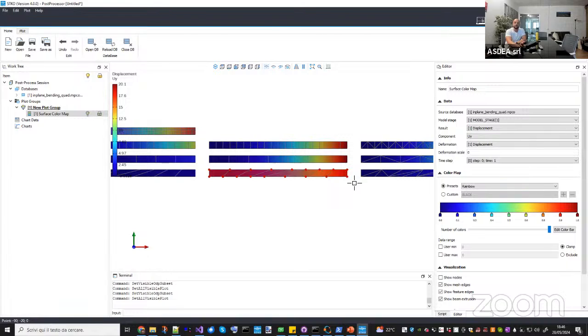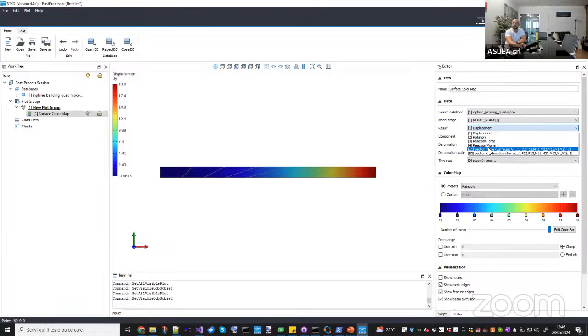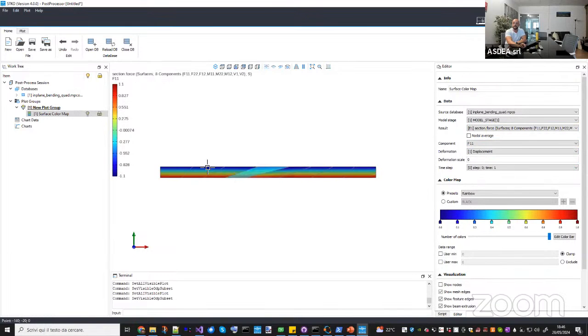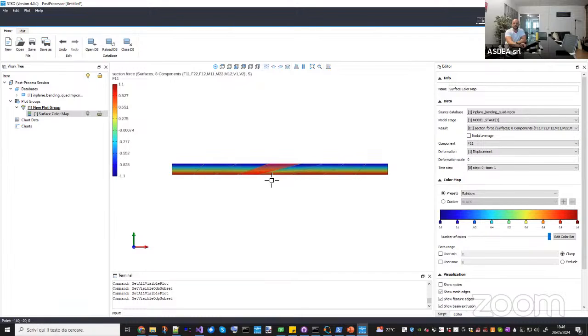Also, in this case, as I said, the formulation that we used for the in-plane behavior is almost insensitive to mesh distortion. It's completely insensitive to aspect ratio distortion and almost completely insensitive to this very strong distortion. As you can see here, the displacement is also almost 20. And if I look at the stresses, they are still very good, okay? So you have 1.1 instead of 1, but basically the error is given by the central element, which is the most distorted. If you get rid of those two, you still have a good solution here, okay?